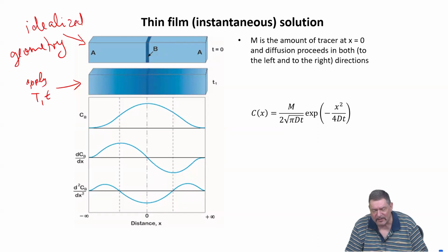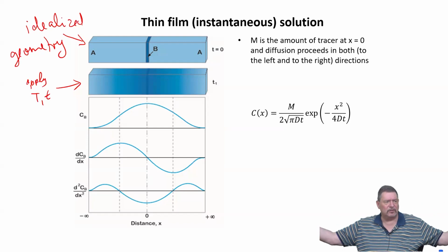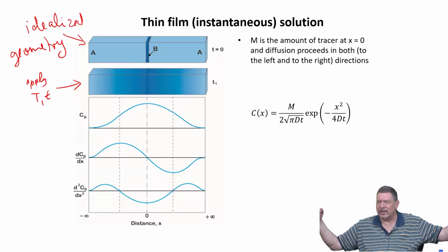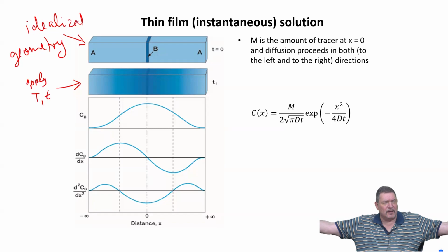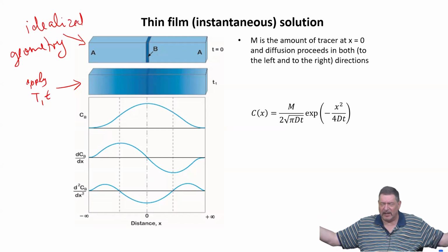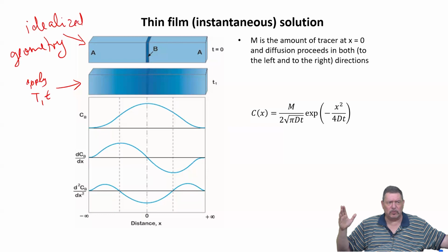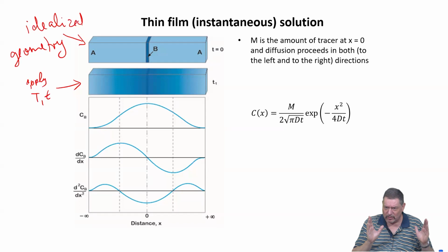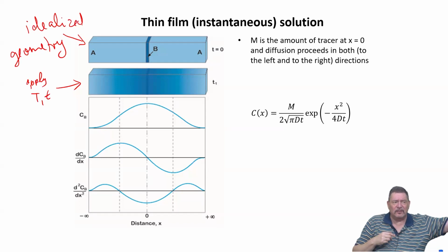And then you get this distribution, which is indicated by the slightly darker bluish color being washed out towards the ends. So B was diffusing into A to both sides because the situation is symmetric, and probably the time was not enough for B atoms to reach the far ends, which is also important for the boundary conditions of this type of solution, because the infinite half volumes A should be so large that within the experimental time t at temperature capital T, the end should not be reached.